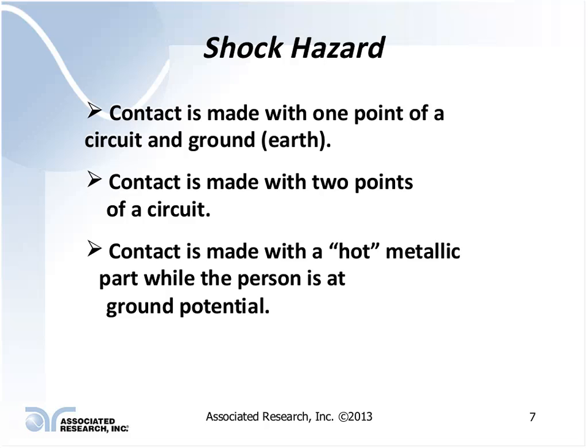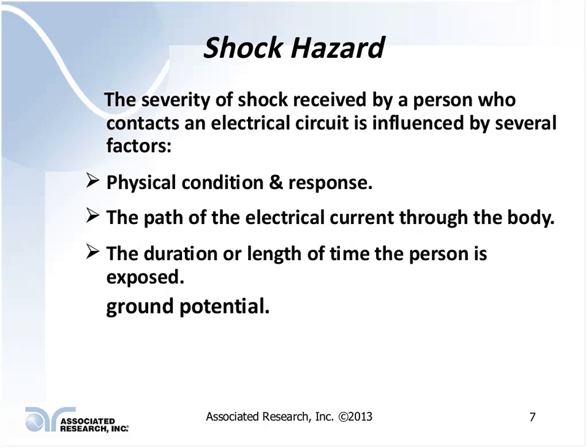And if that ground circuit is open, as soon as you come in contact with it, you've completed the ground path, and that shock could be lethal. There could be enough current flow through your body that could result in your heart going into fibrillation, or just your heart stopping, or at the least maybe a severe burn. So there are quite a few different problems it could result in, defeating a primary safety feature of the product itself, such as the ground circuit.